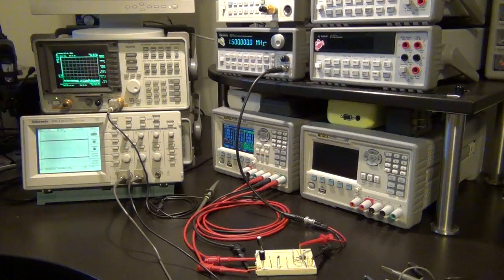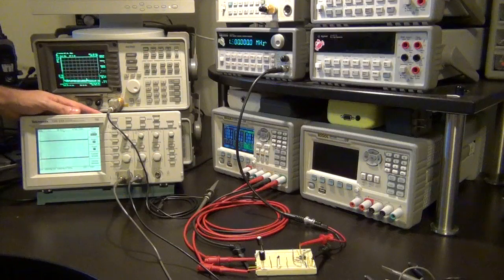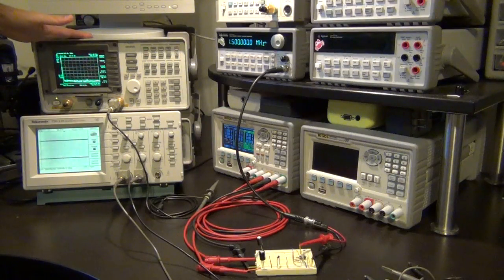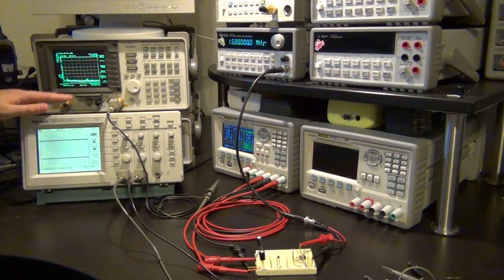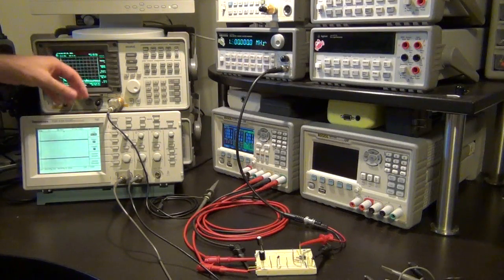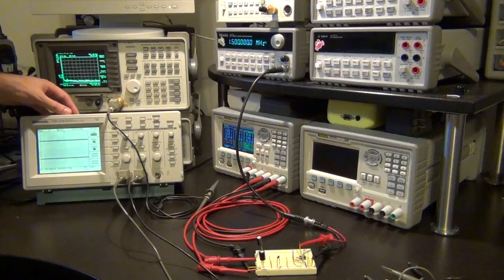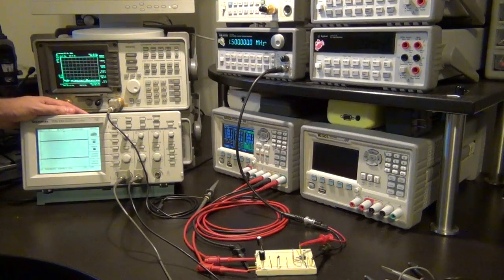So let me explain what the setup looks like. I have an oscilloscope, the Tektronix TDS210, so I'm going to look at the signal in the time domain using this instrument. I also have an Agilent 8595E, so I'm going to look at the spectral content of the signal on this instrument. Now some of you may ask, well, why not just use the FFT function built into here? Well, there are two reasons. First of all, in this one, once I take the FFT, the screen becomes too cluttered with all the information because the screen is only black and white.